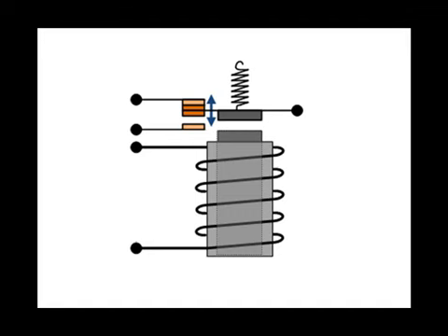As this presentation continues, it will become apparent why a short discussion on relays will bring a more clear understanding of programmable logic controllers. The programming language used to create or write programs for a PLC, programmable logic controller, is based upon relay circuit symbols. The original relay control panels use relays for the logic, and the most common programming language today for PLCs is ladder logic. This language evolved from the symbols on the electrical prints.